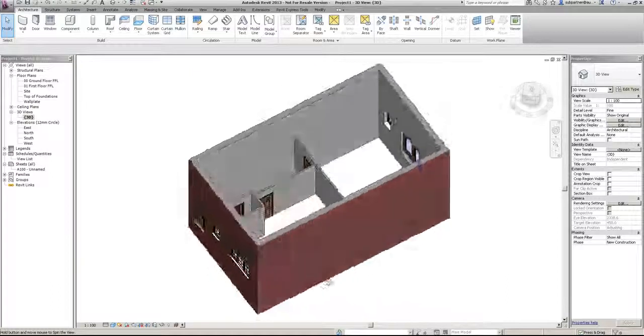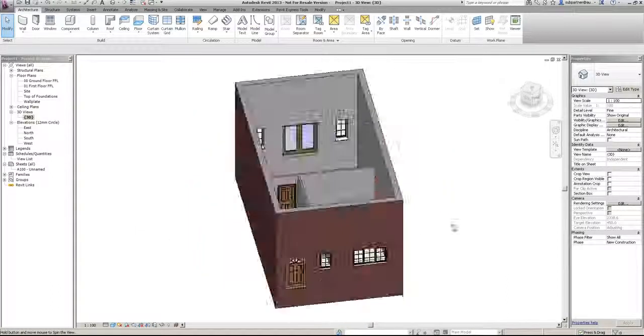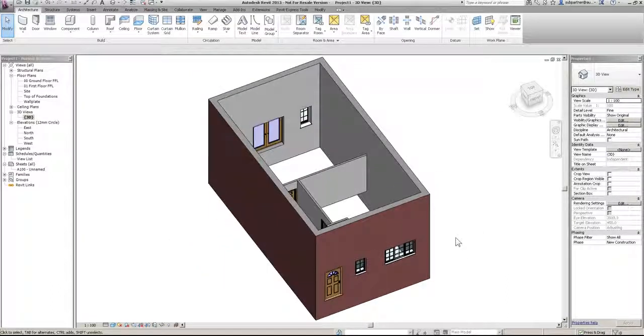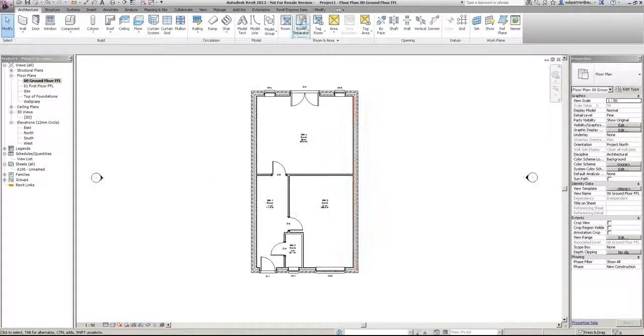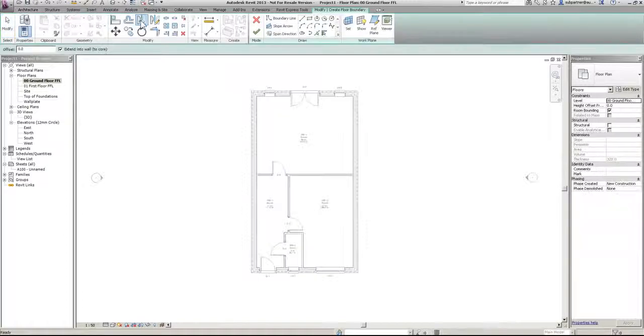As you can see, we're starting to build that up, but obviously because we're working on a BIM model, we're going to have to decide what's going on in the whole building, and we're not just talking about a floor plan here. We want to see what the floor constructions are going in here. So very quickly, I'm going to go back to my ground floor level. Okay, and I'm going to go to my floor tool. I'm going to choose a beam and block floor, and basically when you do a floor you have to draw a boundary and it will put a floor construction within the boundary.